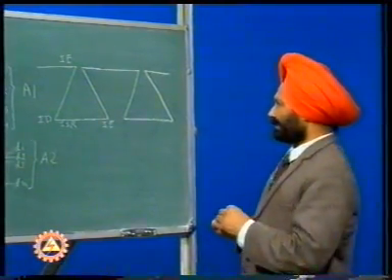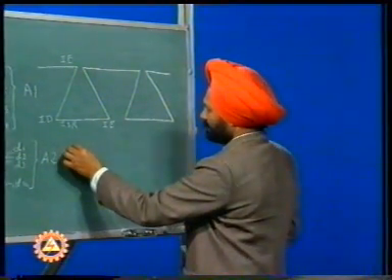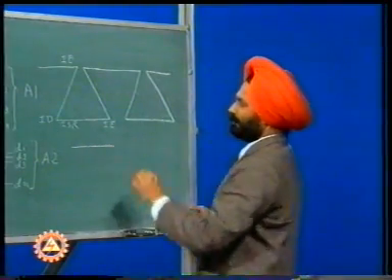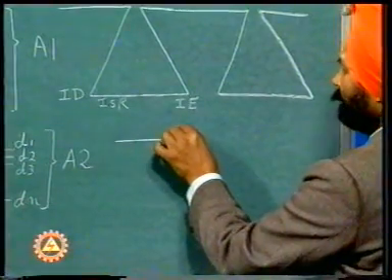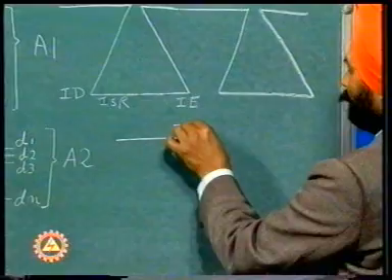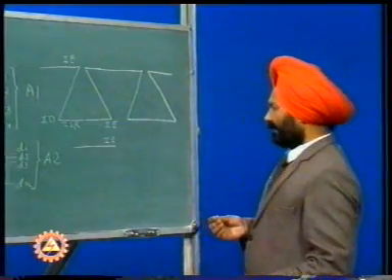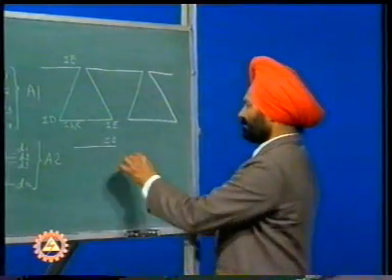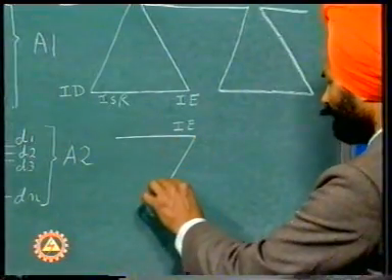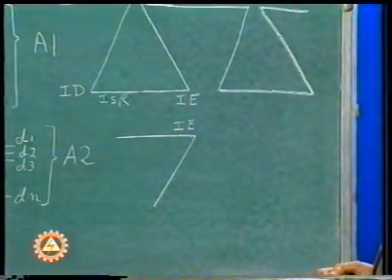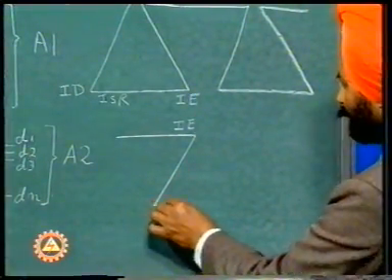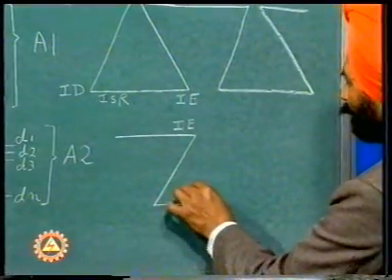In that case, suppose the microprocessor is running its main program and its interrupt system is enabled. Say if any interrupt comes now, then the microprocessor will automatically branch to its corresponding interrupt service routine, say ISR1.